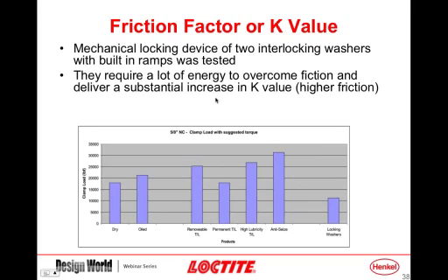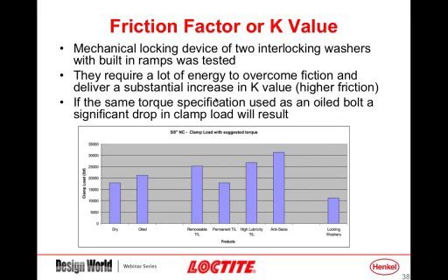And this just summarizes that ramp system. So again, key being, if you are changing the type of thread locking system that you're using on a device, just make sure you've similarly adjusted the torque that you're going to apply so that you achieve the clamp load, always keeping in mind that the objective of a fastener system is to get the design clamp load that you have for that system.